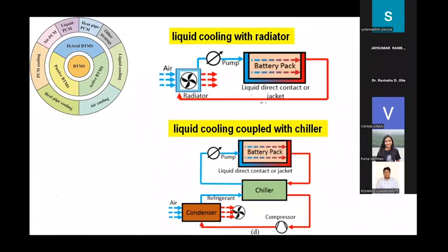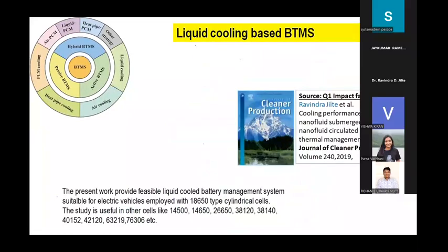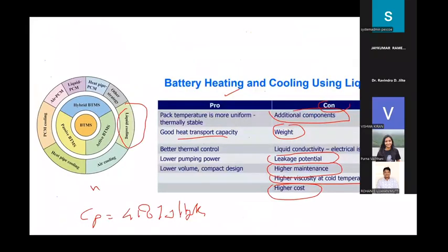Again, same thing, we can use the battery pack, we can circulate the liquid, and that liquid can be cooled with the air. Options are available: liquid cooling with the radiator, or liquid cooling coupled with a chiller. We have adopted the situation called liquid cooling based BTMS. But now if you take water as the working fluid or heat carrying fluid.